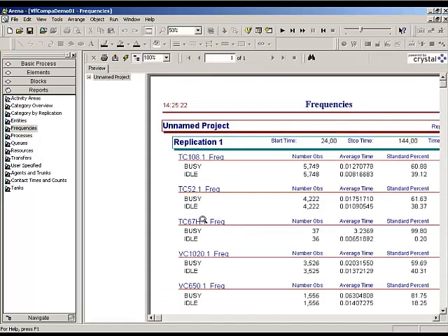and if I look at how the machines behave, I see that I have 5 different machines, and here I have an idea of their saturation. So I have a percentage that says how much of the time the machine has been busy, and the percentage of the time in which the machine has been idle. And if I look at the result, I can easily understand that there is this machine that is the bottleneck of the system because it's been busy for 100% of the time, and so this machine is the one that is limiting the performance of my system.